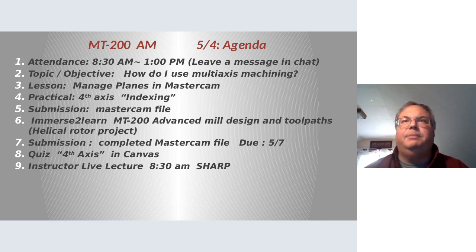In the old days, before Mastercam was popular and the capabilities of the cam systems were what they are, they used to use machinable wax. They would put a piece of wax in the machine and cut the tool path into that, because if a tool holder collided with it, or the shank of the tool or something, it wasn't going to damage it.